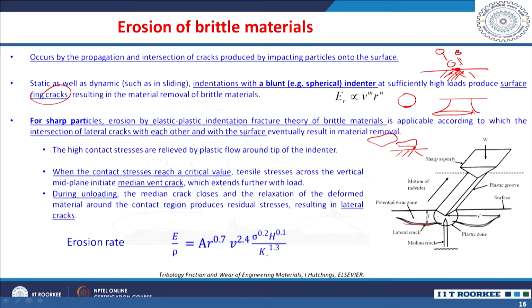So, the high contact stresses are relieved by the plastic flow just around the tip of this indenter. Indenter, I mean the sharp particle with a sharp edge. When the contact stresses reach a critical value, tensile stresses across this vertical mid plane initiate these radial median cracks.